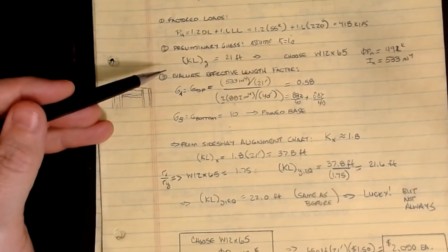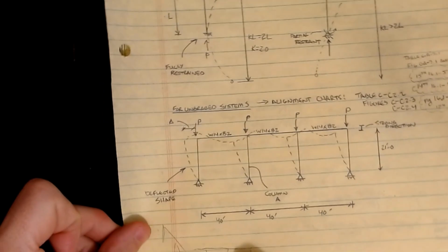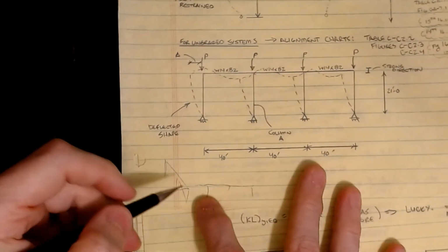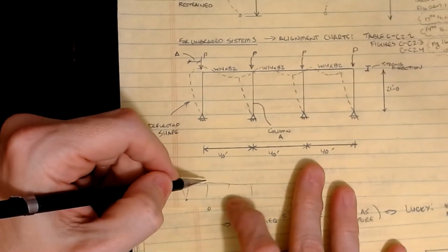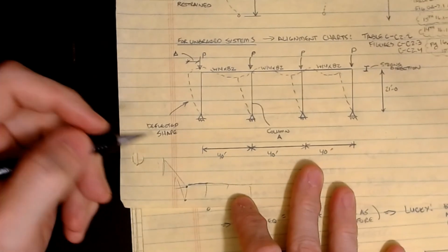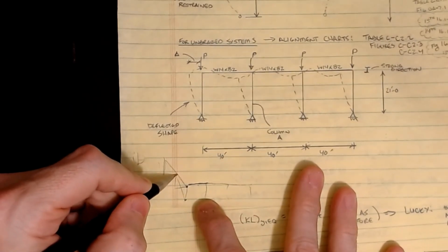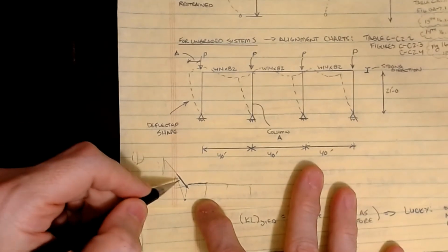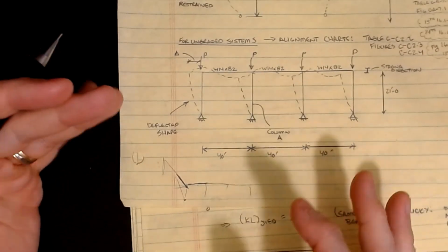All right, so where we had that picture that we drew a little bit earlier, kind of down at the bottom, when we were looking at this picture here, this may be my A node and that may be my B node, and we were looking at this frame in that direction, and these were the beams that went into A. When you turn and look the other direction, it's the same column with an IY value, and now you have to consider the pieces coming in from that direction if we didn't have any framing or any sort of statement like that. So I hope that's kind of made sense to you.